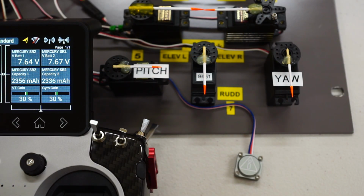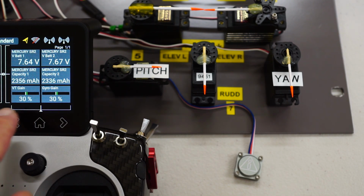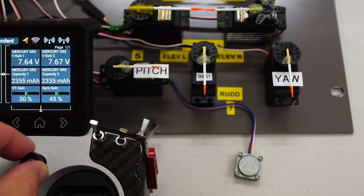So now we can see the servos, and I've included a little bit of the screen here, so I want you to keep an eye on this vectored thrust gain channel. At the moment we've got 30% on both the vectored thrust and also the standard gyro gain. This is impacting our ailerons and elevator and rudder. However, this gain here has no impact on the actual vectored thrust nozzle.